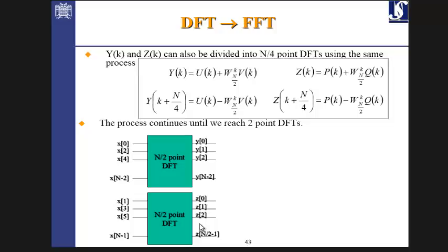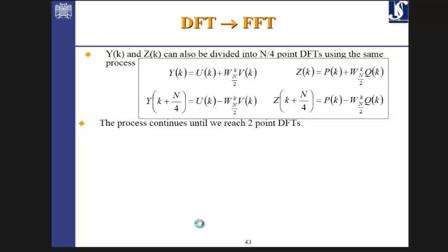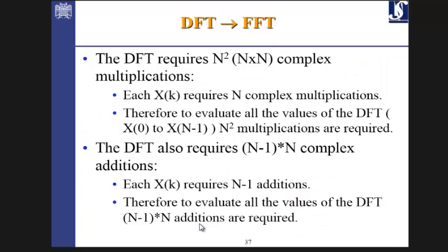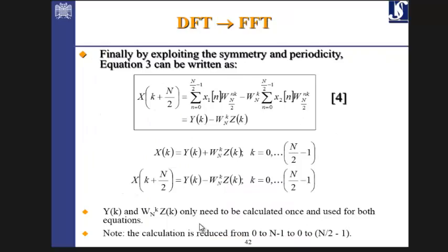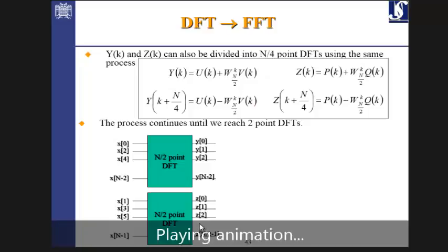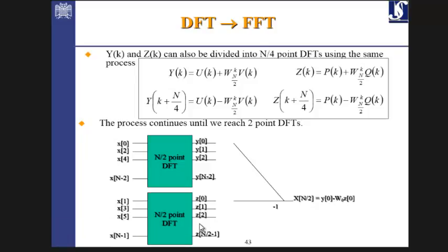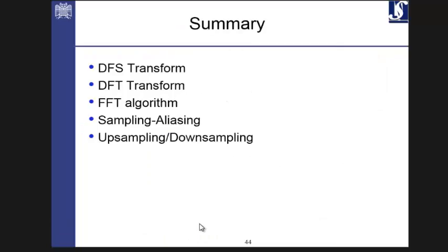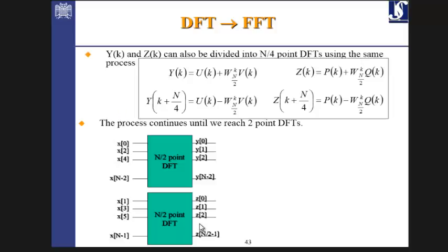Implementation of the DFT in this form, even though the original one had the order of n squared, I mentioned here that the original DFT is actually n times n complex values, that will reduce to n log n order of computation. So you see that we take this, we take the other one for the next sample, and just by doing that, you can create a very nice representation of the DFT using different steps, different layers of radix 2. So radix 2 means division by 2.